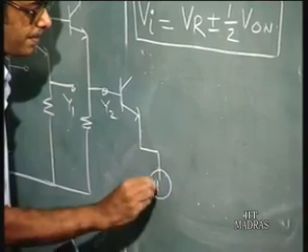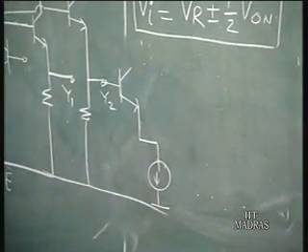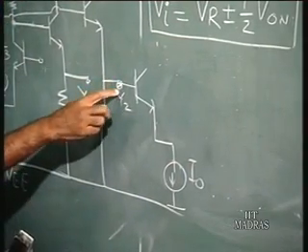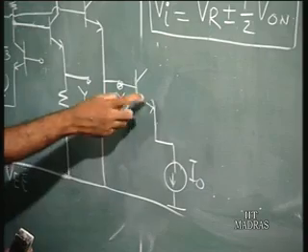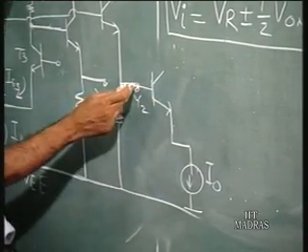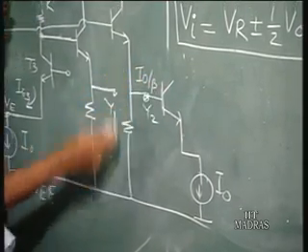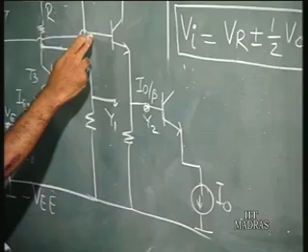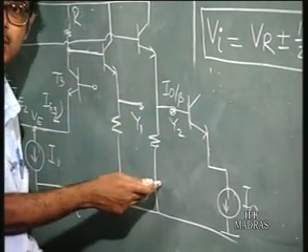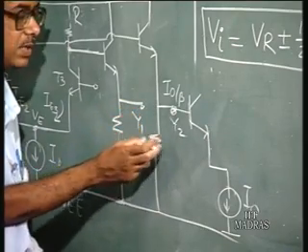again you have a current I naught here. So this voltage Y2 is logic high, say. So this transistor, the next stage, is going to conduct. So if this is I naught, the base current is I naught by beta. And what is the current on the base here? Because there is I naught by beta, plus a small current. This is usually a high resistance, so this current is much smaller.